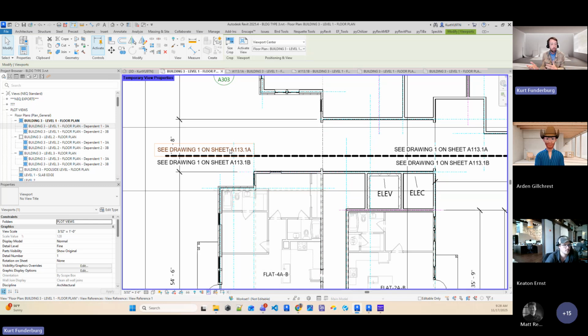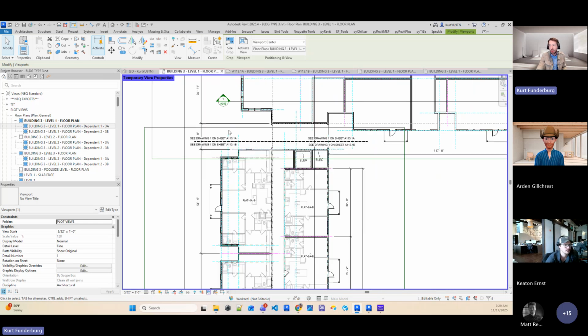It's a really helpful tool to segment the building and show certain pieces of it without having to go deeper and use text. If you wrote that 6 times, it might not seem big, but if it moved, you are not coordinating how it moved, or the sheet number changed. This is all picking up that information of where the view lives and how it's being applied throughout the drawing set. So that's kind of the gist of scope boxes, match lines, and view references.